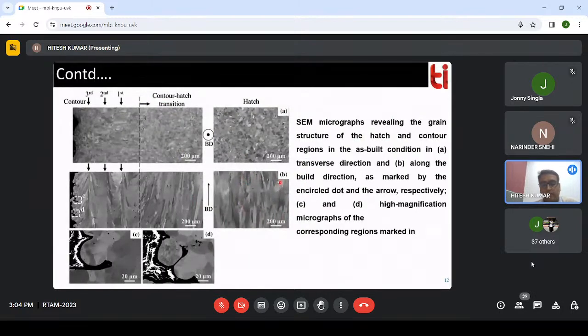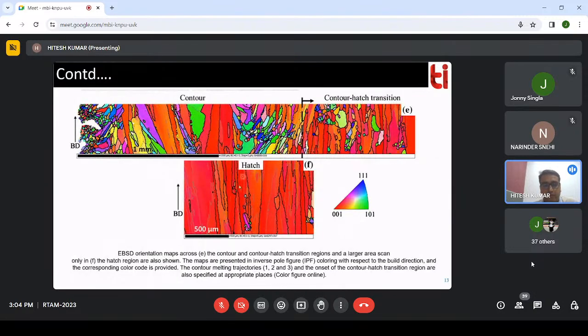But if we talk about the H direction, as observed earlier, this is going to be columnar growth. So the same structure we observed in this. These are the columnar growth structures. Parallelly, we are getting some low angle grain boundaries. Low angle grain boundary means there is misorientation, so the grain boundary is mostly either tilt or twist. Those types of structure are basically observed in the H direction.